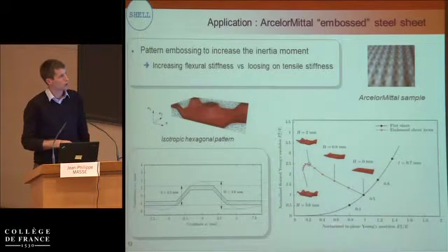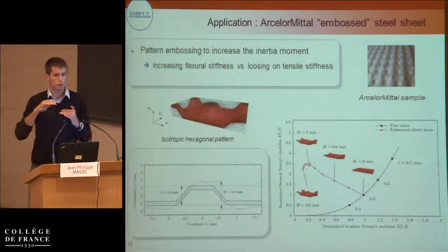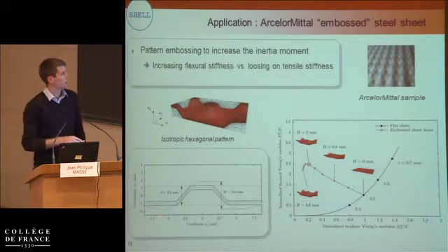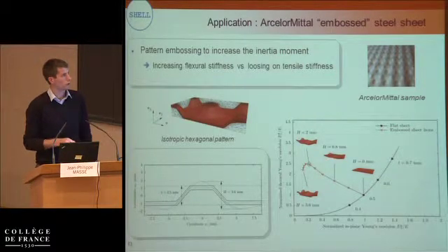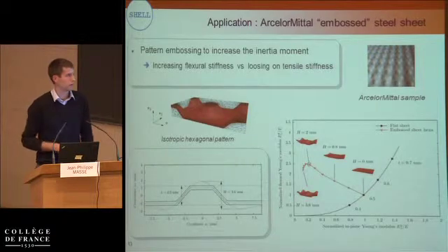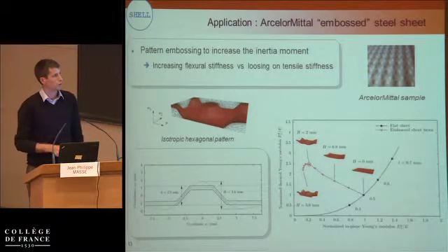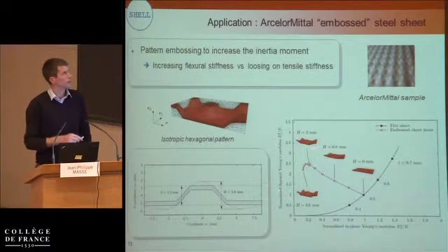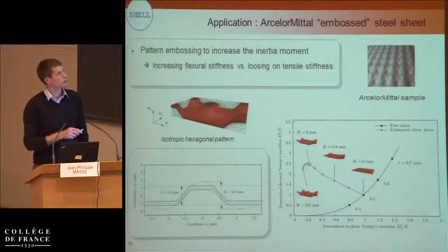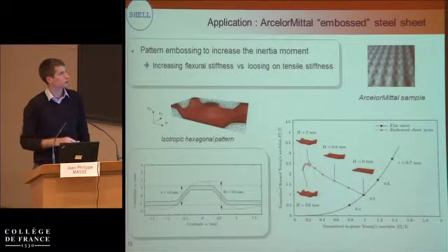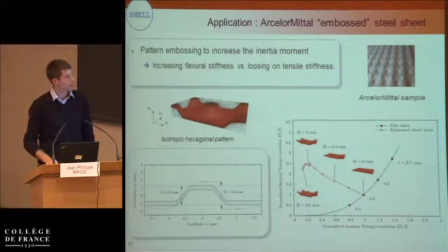This is the curve up to a maximum, which is when we reach the bounds we chose for the height of the corrugation, and after that the flexural Young's modulus decreases. One conclusion is that this type of geometry, which is capped here, is not efficient, and the best one is when you reach just the bound.